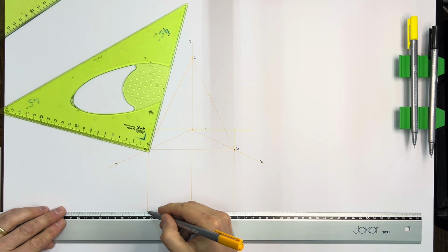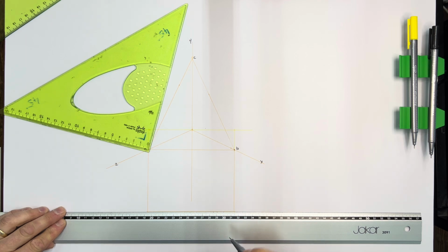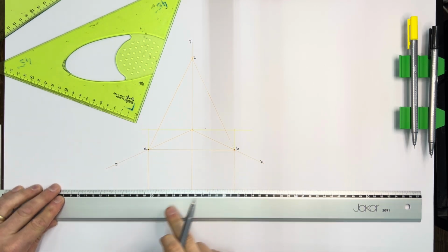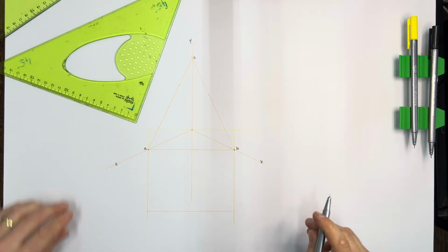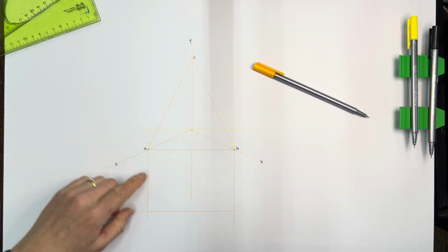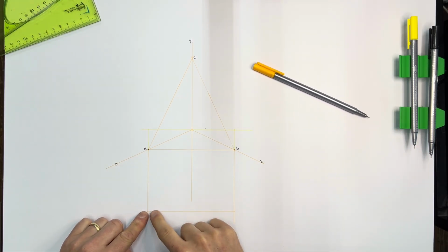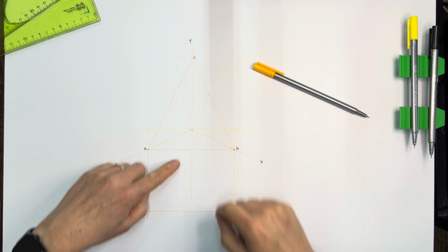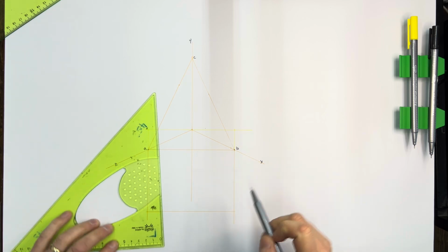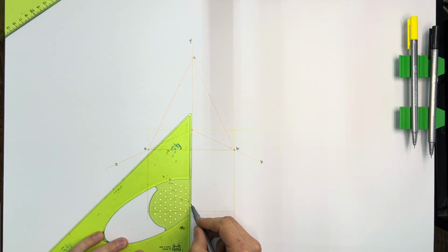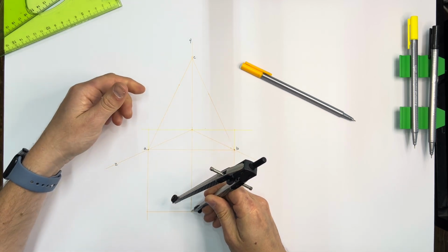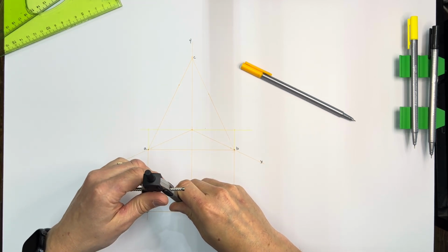As far down as I'd like, I'm going to draw a construction line parallel to the line AB. Because AB is horizontal, this construction line is parallel to it. I could bisect this line, and you usually bisect the line to draw the semicircle, but because this is an isosceles triangle, technically this is the bisector. I should have projected it all the way down to there. Compass on the midpoint, and draw your semicircle.